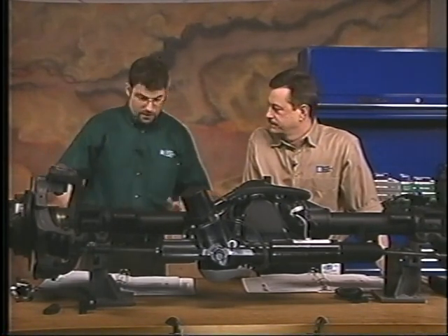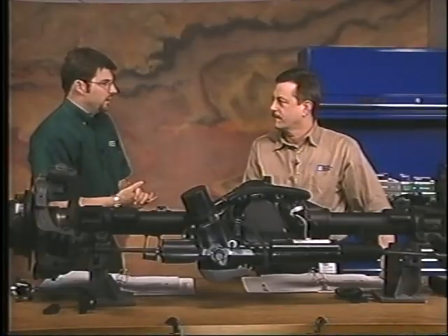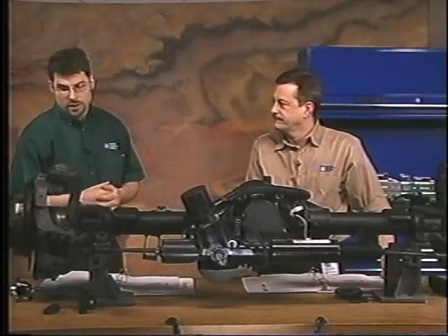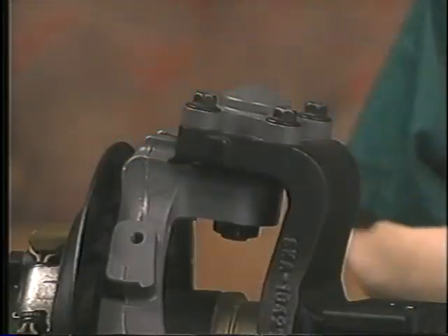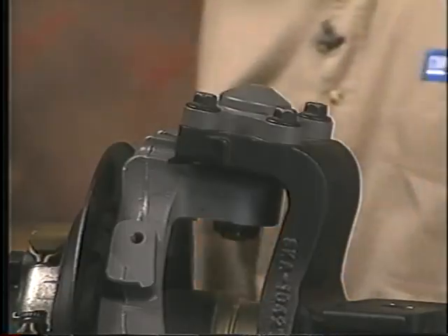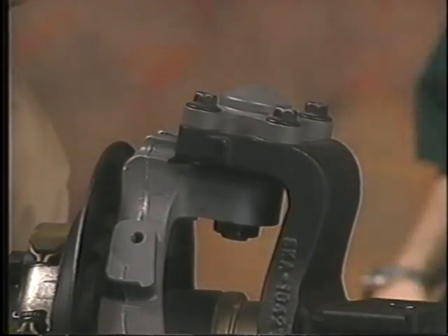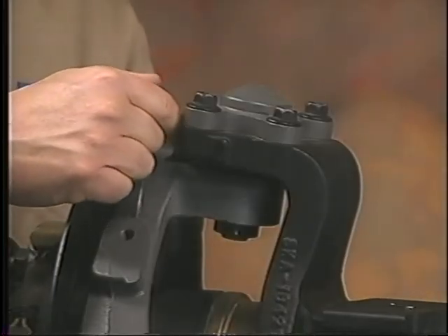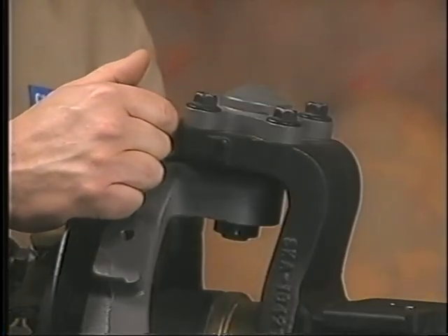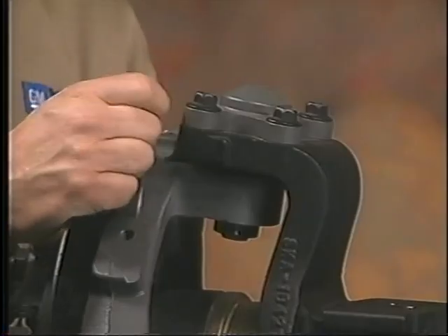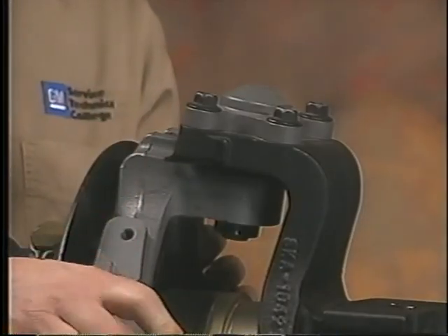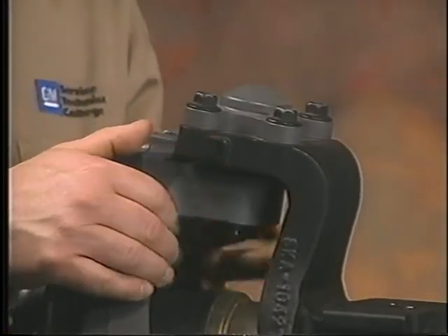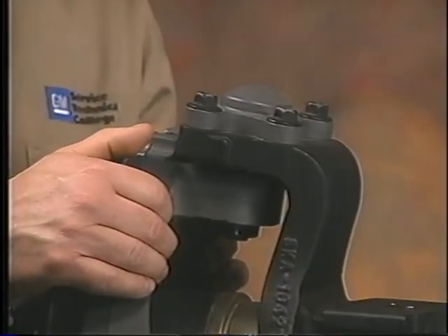Okay, Mike, got to talk about a couple more things here. We've got another safety-related piece of information on our pinch point. Absolutely, let's take a look at that. Now, this is kind of similar to the front steering here. If these wheels are moved a little bit from the straight-ahead position, there's a bit of room up here where you can get your finger in there, so it becomes a pinch point. If the wheels were to move a little bit, you know what? It's going to hurt. If we remove our tie rod, then this whole assembly could float a little bit on us. It could pinch, and it would hurt.